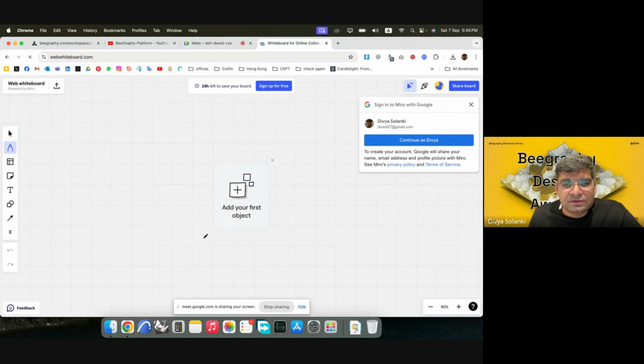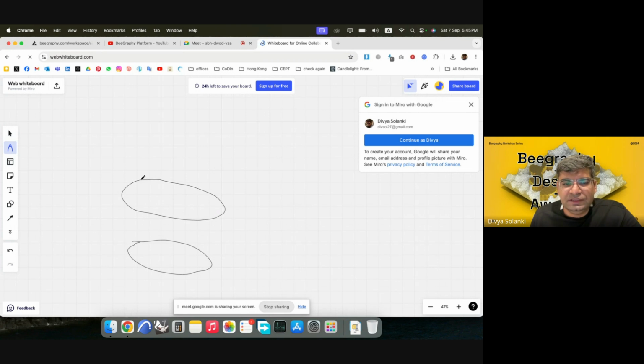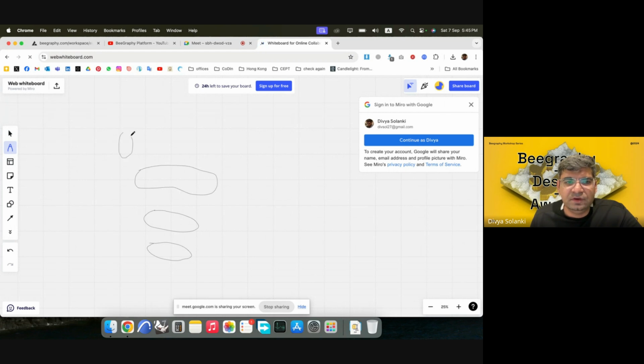Yeah. So I'll just explain the logic behind the mannequin. It's basically a series of lofts that you can do. It could change as per the measurements that you are taking of the subject. It could vary as it goes up. You could also incorporate the arms. And once you loft through all of these, you would be able to generate a mannequin.